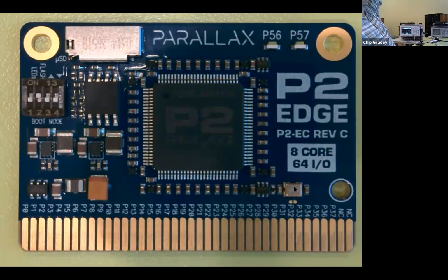So it's running off the core voltage of 1.8 volts. It comes in here to a cap, comes out here, and then there's a series resistor, well, kind of a parallel resistor with the first inverter. So what that does is it squares it up. And then it goes through two inverters that are running at 3.3 volts, and then it goes up here to the XI pin.